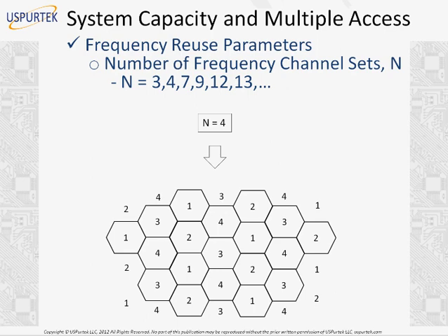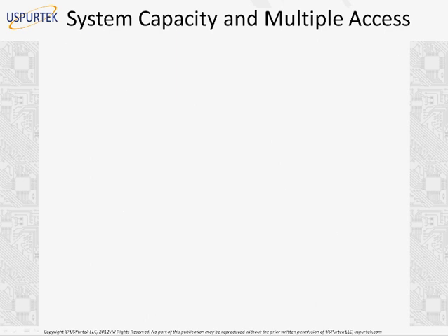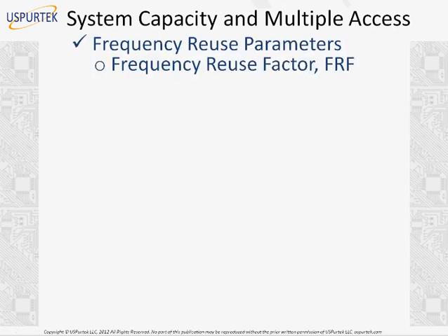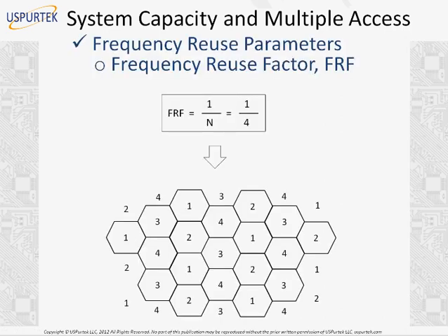The time slot allocation will depend on what standard you use, whether you use GSM, CDMA, or if you are using FDMA at all, because in CDMA you don't use FDMA. So if you use GSM or LTE, what type of time slots you're using will be covered in future webinars when we cover each protocol in more detail. But here our focus is that we are trying to reuse frequency spectrum in different cells, and how do we do that, to avoid co-channel interference.